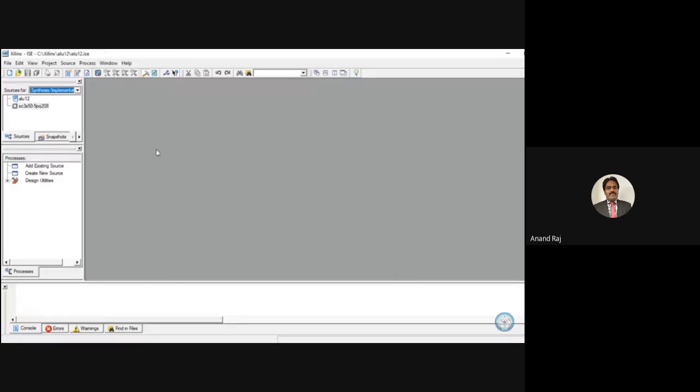Okay. Now make sure that the device name along with the speed and the total number of pins are properly displayed once you create the project successfully. Now we have to open the editor window to write our Verilog code. I will select a blank text file.